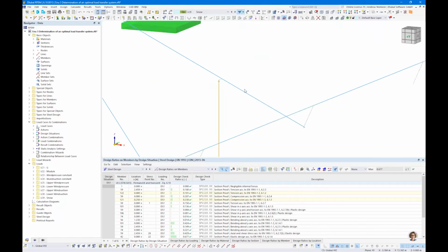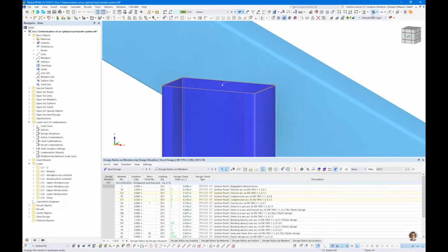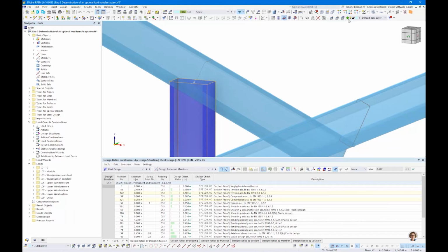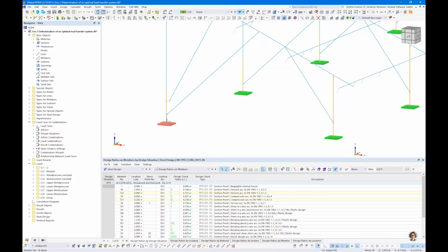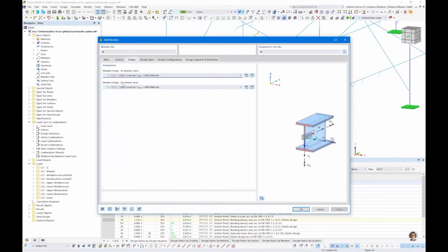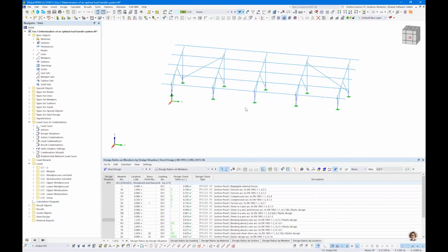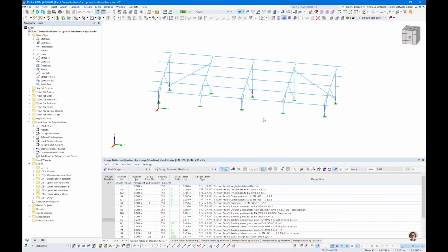but in both directions. For example, also here the situation of pile to the rafter. You see you have really different eccentricity dimensions. Further, you have also some connections between members to the other members. So the engineer here used hinge definitions to take care which type of forces are transferred here. So all these options could be considered in the environment of RFEM to find a good equilibrium and to find a design close to reality for your decision.